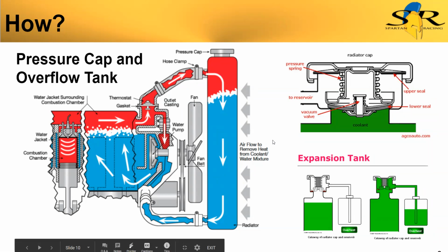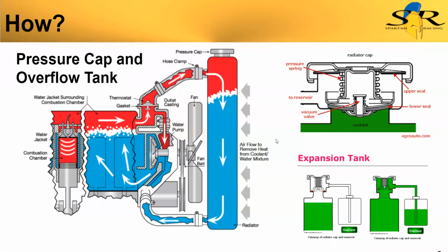So it doesn't create a vacuum as it cools down, because when you create a vacuum, that's a low pressure, and coolant or water boils at even lower temperatures than it would at atmospheric pressure.